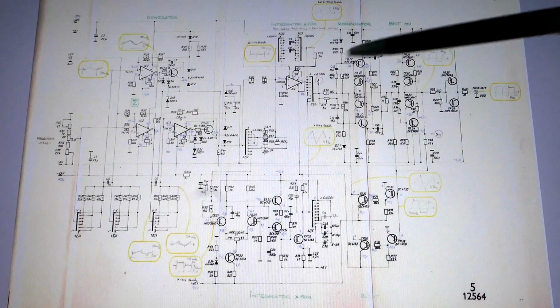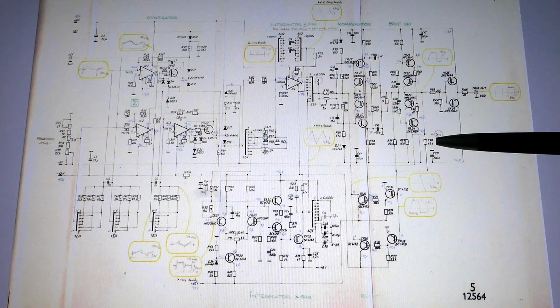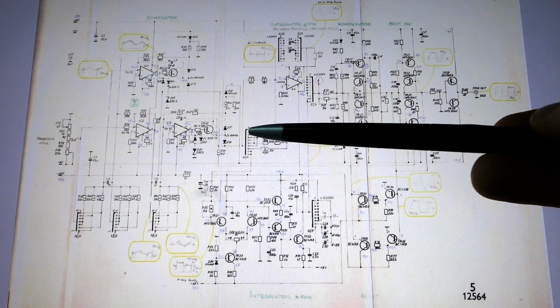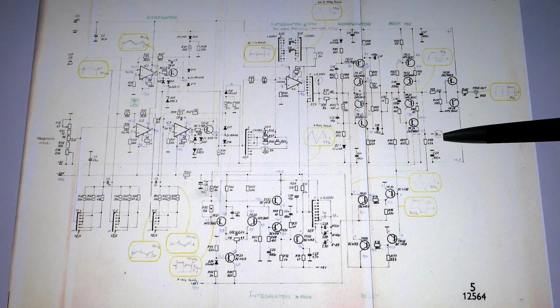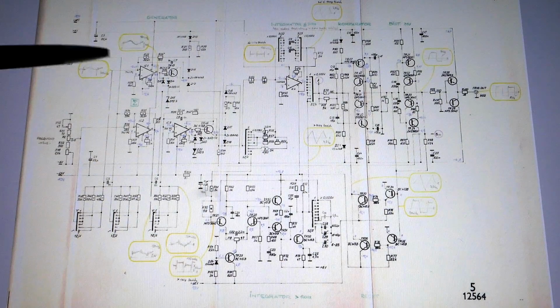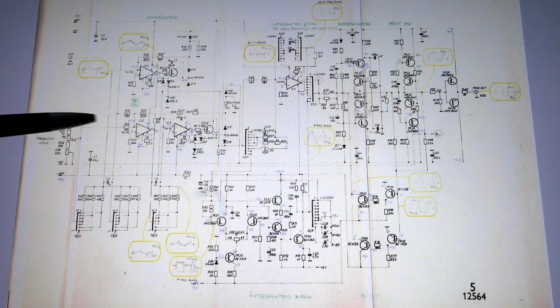I don't think the problem is anywhere here, because the square wave coming out of it is symmetrical. I mean voltage symmetrical, not time symmetrical. The voltages in the positive and in the negative half cycle are the same magnitude. If they were not, this would influence the duty cycle here, but given the positive and negative half cycle is at the same amplitude, this has to be working right, and I guess the problem has to be somewhere here. And another reason for this is that it only happens in some positions of this potentiometer.